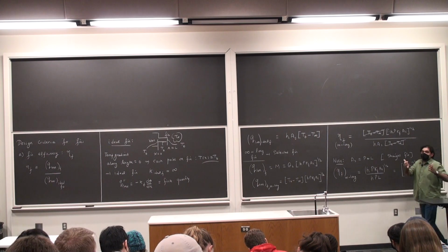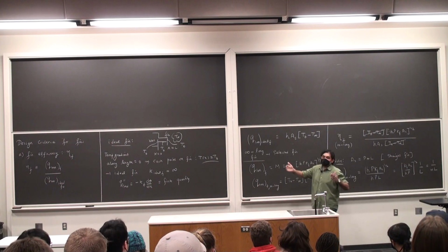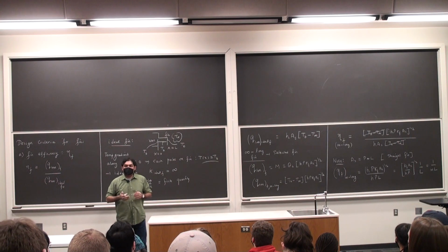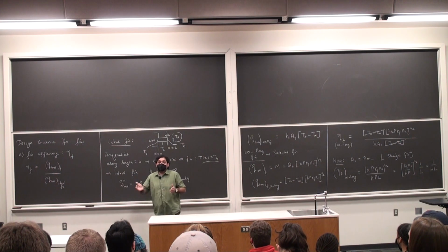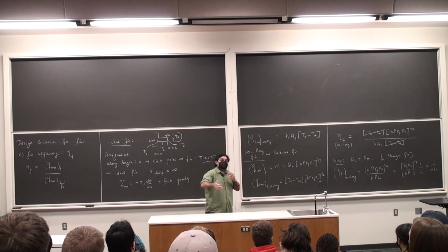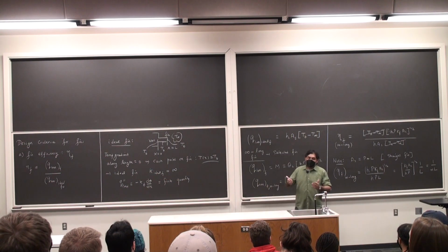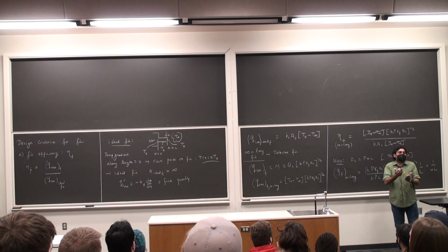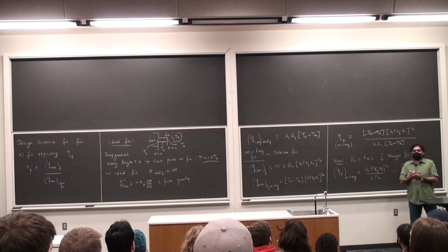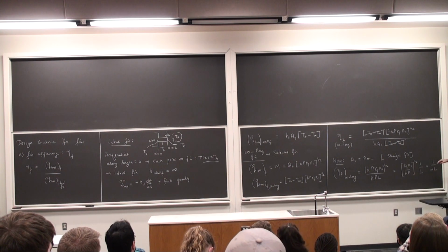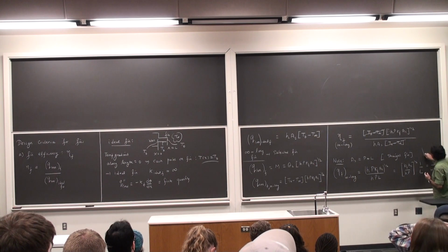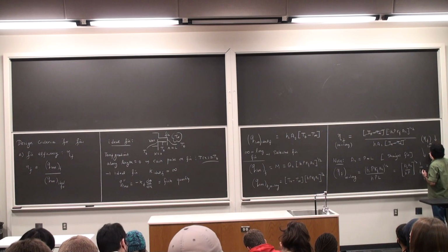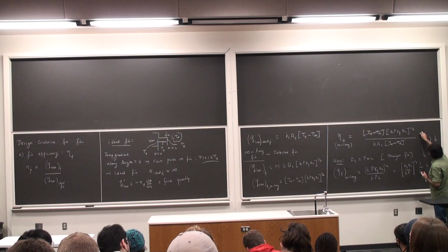which absolutely tells you if I am actually literally thinking of a fin that is infinitely long, then that is a losing proposition, because the efficiency is going to drop down to 0. So we do not obviously want a fin that is really so large that its efficiency is gone. We operate under the criterion that for an infinitely large fin, the product of m times L should be greater than or equal to 2.6, and that is sufficient. Okay? So this tells us that the efficiency drops as the length increases. So eta f infinitely long goes down as L increases.